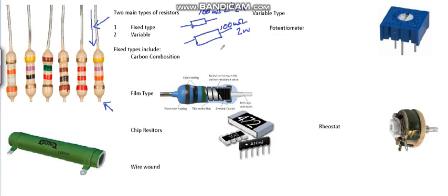They will both have a voltage drop across them that are the same, given the same voltage or pressure. The only difference here is that, well, one, as you can see, is larger than the other one. And you can see that the larger one is a 2 watt one. And the reason for that is because as resistance resists current in the circuit, it develops heat. And if it's physically larger, I have all this area here. If it's physically larger than this one here, then it has a greater ability to dissipate heat. It acts as a heat sink. It allows more air to be able to get to the resistor itself. So the larger it is, the larger the wattage it is.